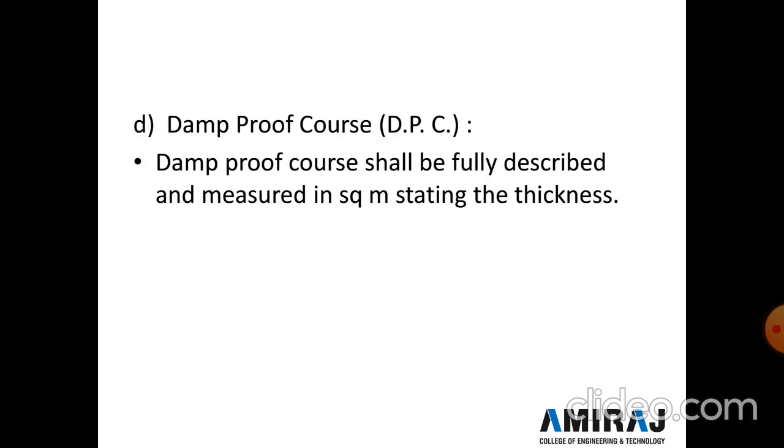Next is DPC. What is DPC? DPC is damp proof course, and damp proof course shall be fully described and measured in square meter, stating the thickness. The item shall include formwork, finishing, leveling, curing, etc. And horizontal and vertical DPC shall be measured separately.